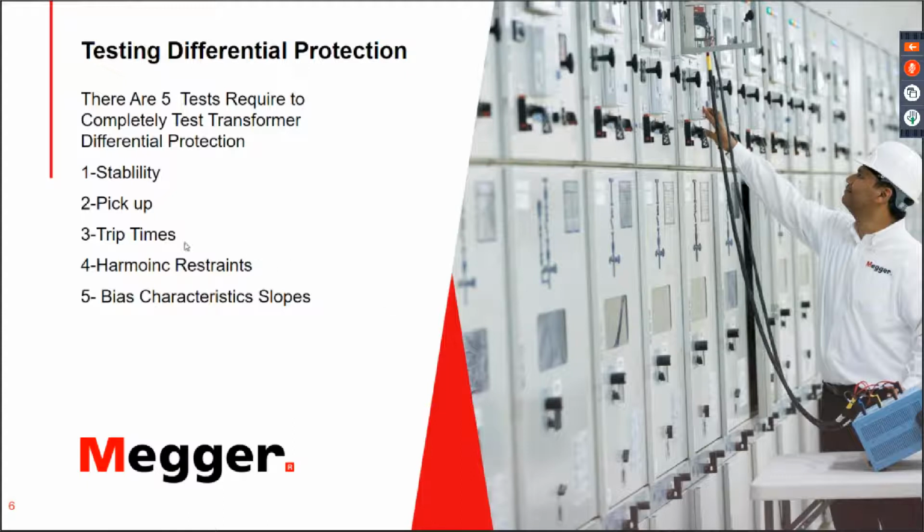Then we will do some harmonic restraint tests. There are some harmonic restraints that are used for specific purposes. We'll see how this test is conducted using the SMRT, and also why we need these harmonic restraints in the first place. And last but not least is the bias characteristic slope. We'll see why we need this bias characteristic slope and how we test it using the RTMS.